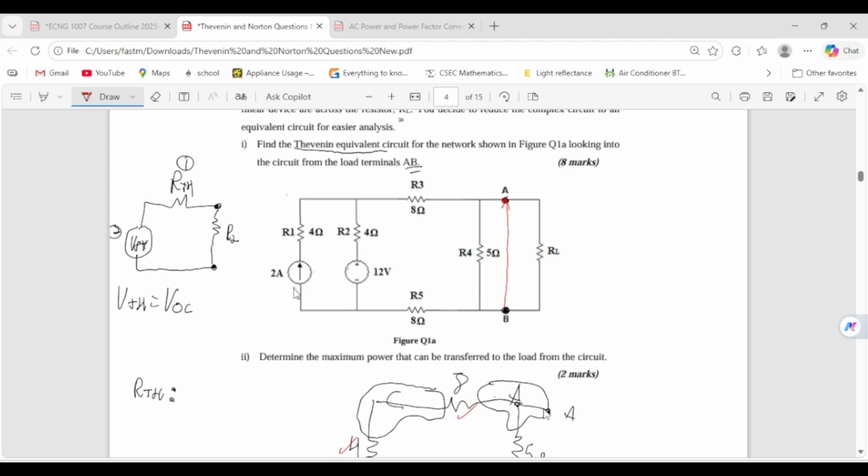So you're looking to see which node will give you the most value if you put it as 0 as the reference. This one really isn't gonna do much, right? But this one will do a lot, because if you make this one 0, you actually know what this node is. So you're killing 2 birds with 1 stone. If you just make this 0, you will have an unknown node here, so you basically end up with more unknown nodes. So you try to pick the node that will give you the most bang for your buck in terms of the reference. So this one will be the best, right? So let this be the reference.